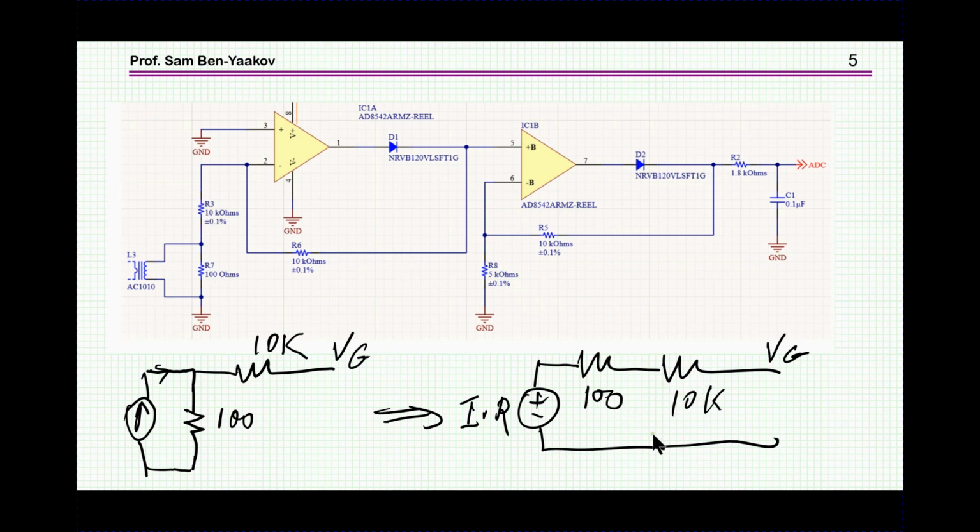So there is an error in this case of, say, 1%. Now, if the function generator put here had an output resistance of, say, a couple of hundred ohms, I don't know what the setup was, then it would cause a lower gain in this path. While in the path of the positive, when the signal is positive, this amplifier doesn't work.